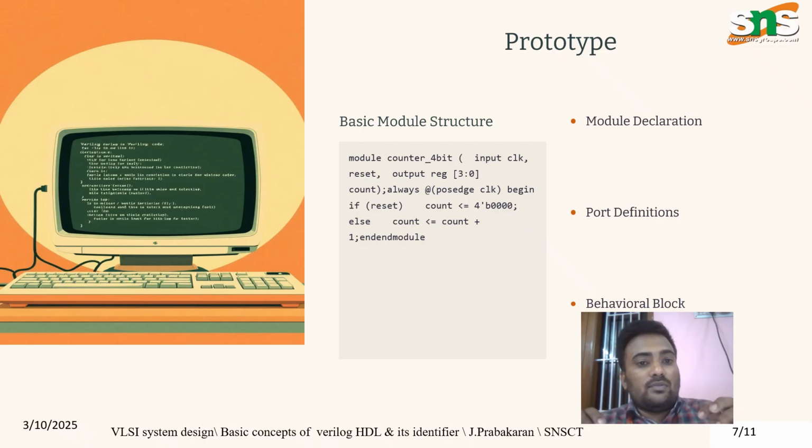This is 4-bit, so you mention 3 down to 0. First two is module declaration. Next is port definition, the input output port definition. Next, here we have used an always block, behavioral block.